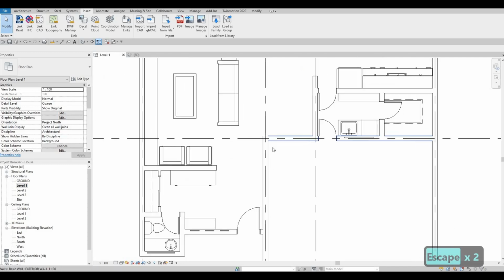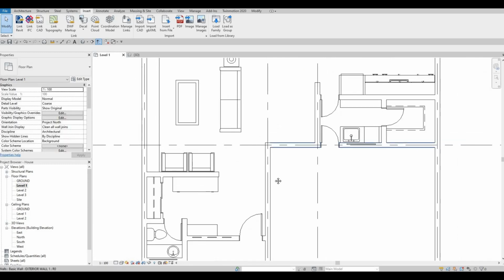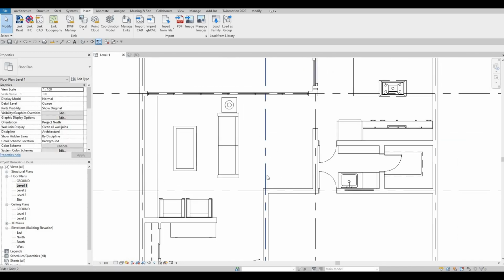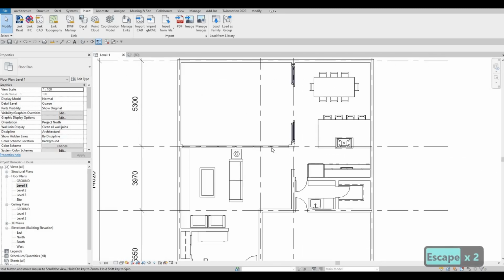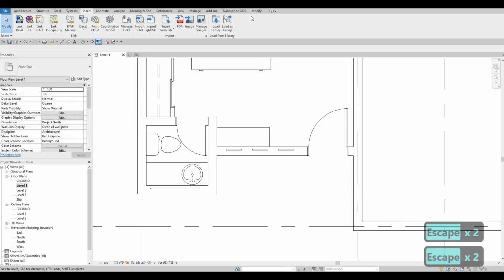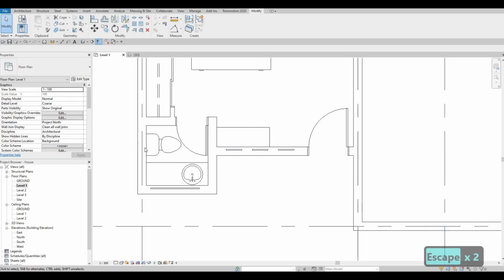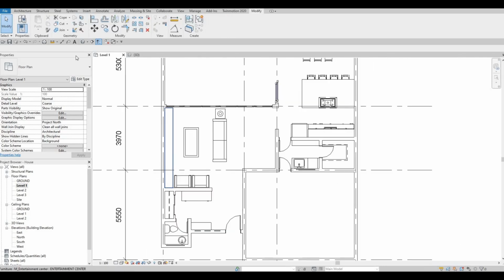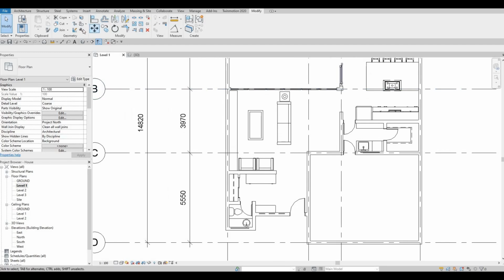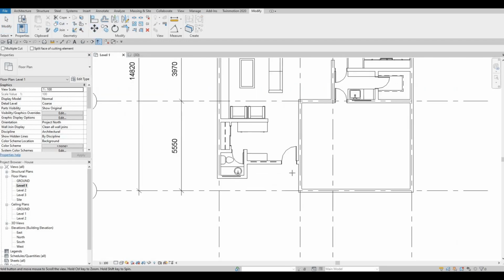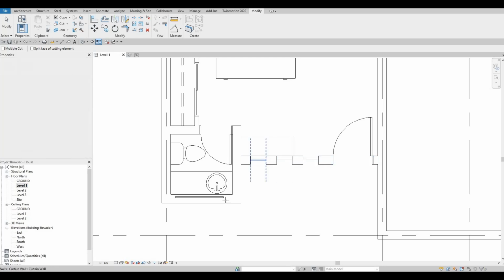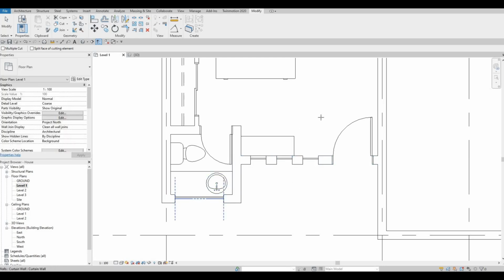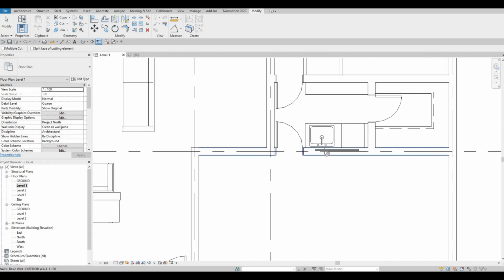And then here what we could do is we could show the stairs, because we're gonna add a stairs right here as well. But before that, let's finish the windows on the first, and then let's add the floor. So here, click on cut geometry, wall first, and then window, wall first, window, wall first, window. So that's the step that you need to do so that you can cut it properly.